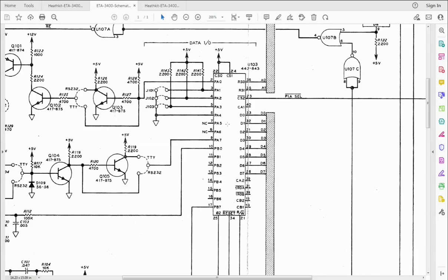So that still doesn't make a whole lot of sense to me, because you could have created a monitor command to set the bit rate and ended up using, with a 6850, much simplify what the processor would have done. And I don't think there was a huge price difference between a 6821 and a 6850. So to me, that's a bit of a mystery, but what do I know, right?